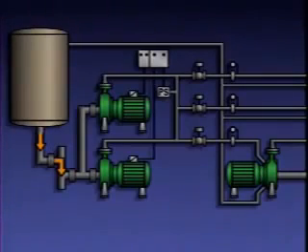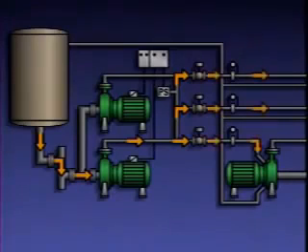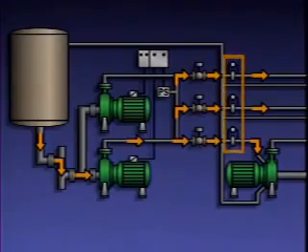The filter removes contaminants from the oil to prevent damage to the sealing system pumps and the mechanical seals being supplied. The pump supplies the oil to the pressure regulators on each supply line. The pressure regulators control oil pressure and the amount of oil flow to each of the mechanical seals. The flow meters allow the flow to the seals to be monitored.